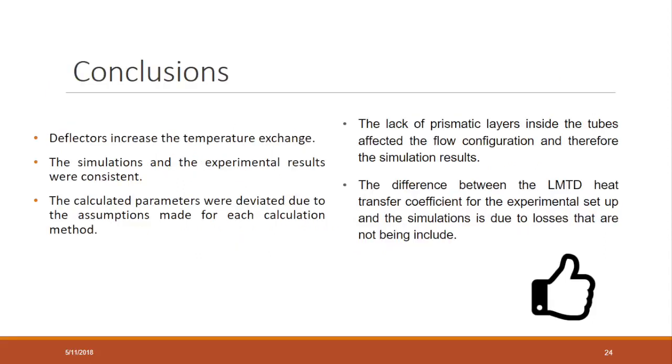Conclusions. Deflectors increase the temperature exchange. The simulations and experimental results were consistent. The calculated parameters were deviated due to the assumptions made for each calculation method. The lack of prismatic layers inside the tubes affected the flow configuration and therefore the simulation results. The difference between the LMTD heat transfer coefficient for the experimental setup and the simulation is due to losses that are not being included.